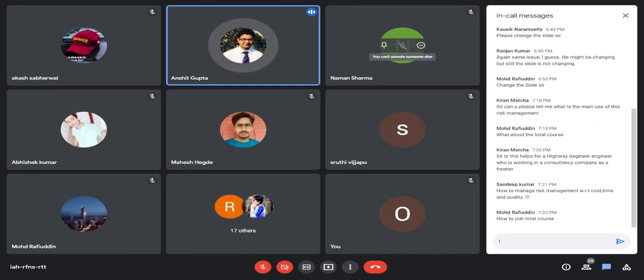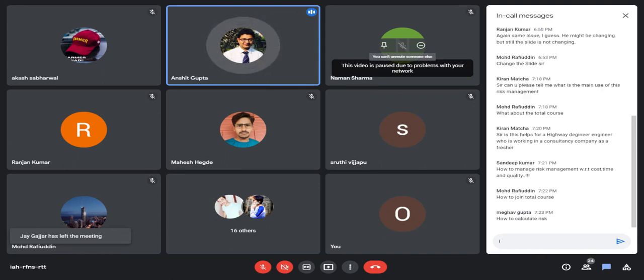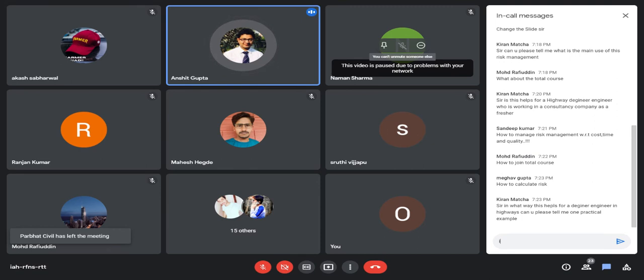It is a recording of every issue at site. Okay, so it helps you, it helps your senior management, your juniors, everyone, and in that way it helps the project in saving cost, time, and quality. Then about quality, for example, if too many NCs, that is non-compliances regarding quality, are coming in a project, then you will add this risk in the risk register, that for the quality department the number of NCs this month is 25. So when your senior management sees in the risk register that there are 25 non-compliances, then they will act accordingly.